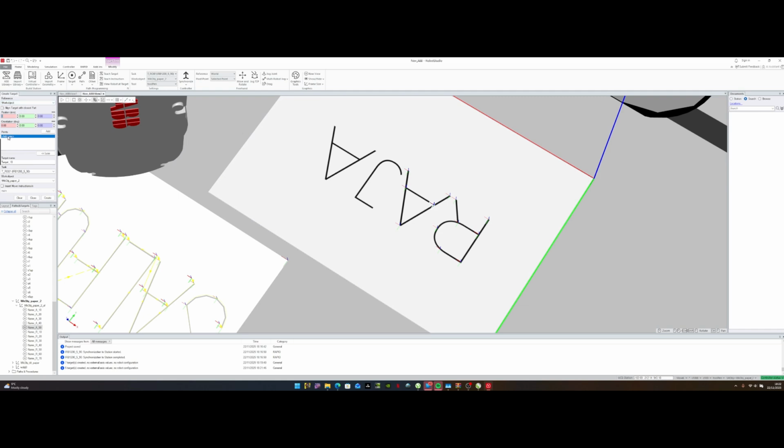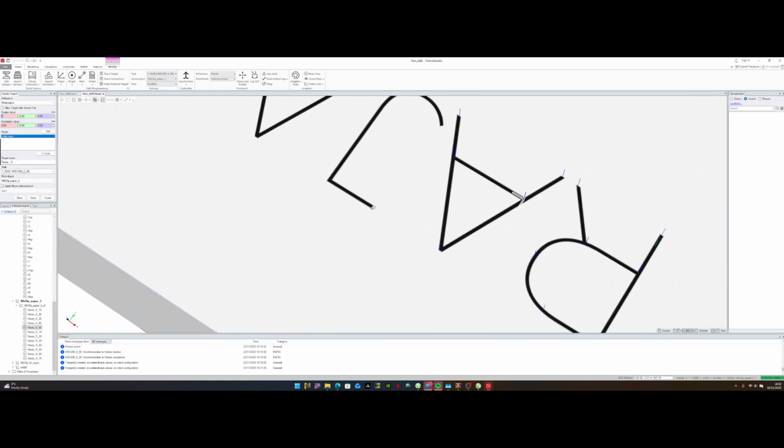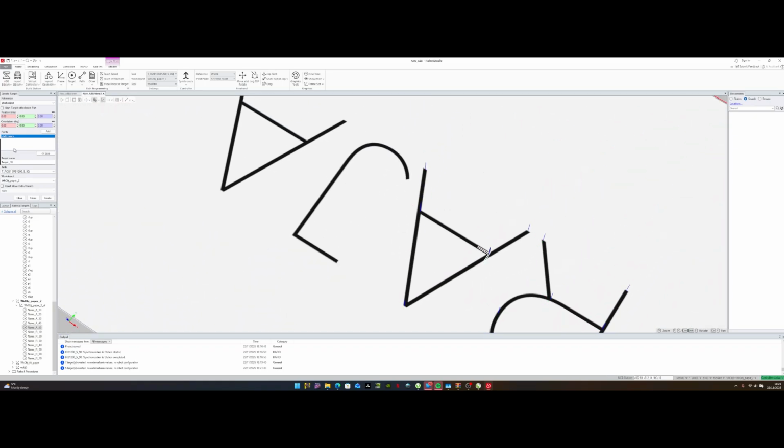So I'm going to click add again. I wanted to do the letter J this way, so let's do it like this. Just going to click add here. First target, second target. Then I'll come over here and put my third target. Then I want it to do a move circular like this. So I'm just going to put this one here and then put this one here. Okay.